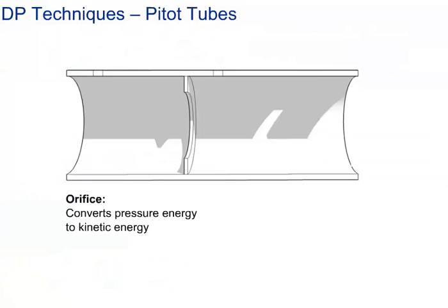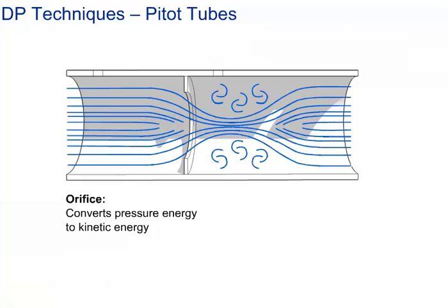A Pitot tube operates in accordance with the same basic laws as an orifice plate, but in a slightly different way. Here we will examine the differences between the two. As the energy in a fluid stream through a meter is constant, then the sum of the 3 basic energy types present, kinetic energy, energy of motion, potential energy, energy of position or height, and pressure energy, is also a constant, ignoring friction losses. In an orifice or venturi, the fluid mass is accelerated through a restriction, which is why such types are often referred to as mass acceleration devices.